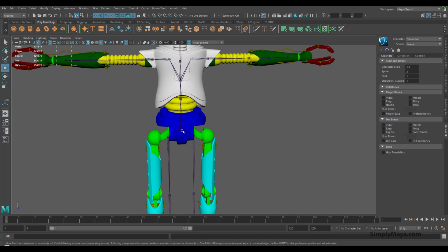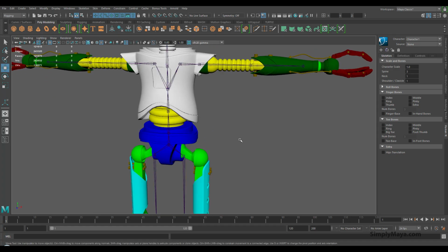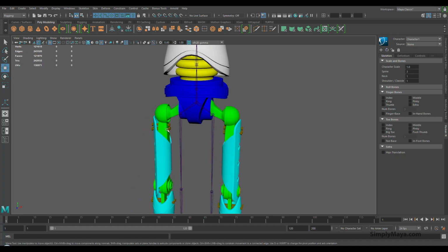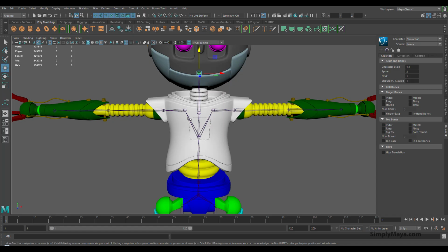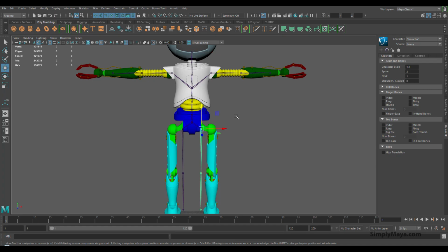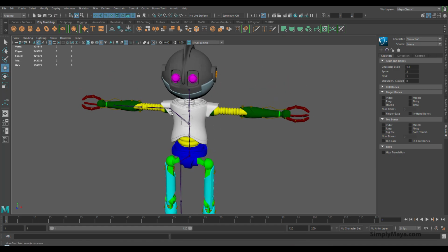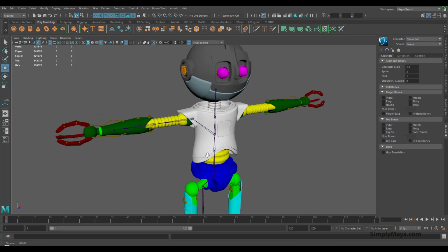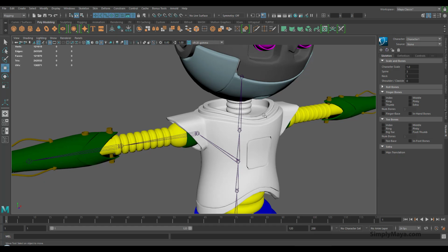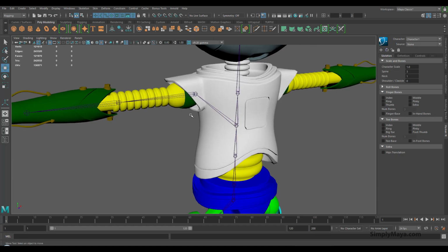We're going to come up. Now we've got just about enough hip joints here. For animation purposes we might create some roll joints, but for simple posing this will do. And as we look up the body, we've got shoulder joints here that we don't really need for this particular character, so I'm going to set my shoulder clavicle joints to 0. Now we need to delete the right hand side of our rig because this character is mirrored from left to right, so it's identical. So we don't want to be repositioning these joints more than we need to. As I say, this is intended to be a very, very fast, quick rig.